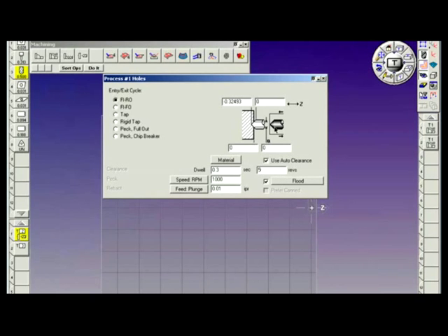The depth of cut when drilling or when doing holes can be defined in one of 3 ways. This dialog here establishes the start of the cut, right on the face at 0. This dialog controls the depth of cut by diameter. If I want to pre-chamfer a hole, I can specify a diameter and it'll chamfer only to that diameter on the angle. Once it passes the angle, it becomes full size. But I can specify a diameter within the angle of the tool.